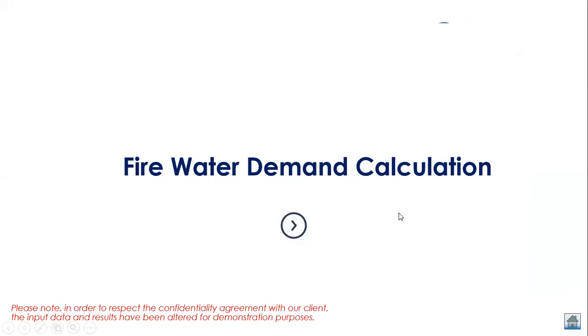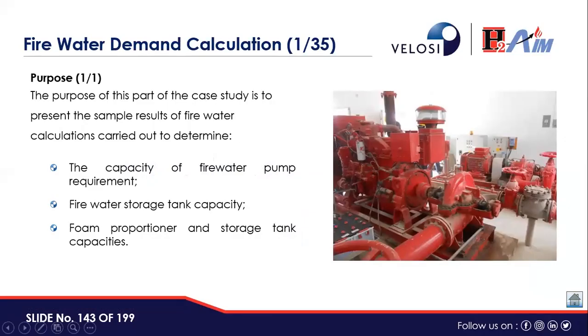Now let us move to the firewater demand. How can we calculate the firewater demand? The purpose of this part of the case study is to present the sample results of firewater calculations carried out to determine the capacity of the firewater pump requirements, firewater storage tank capacity, foam proportioner and storage tank capacities as well.